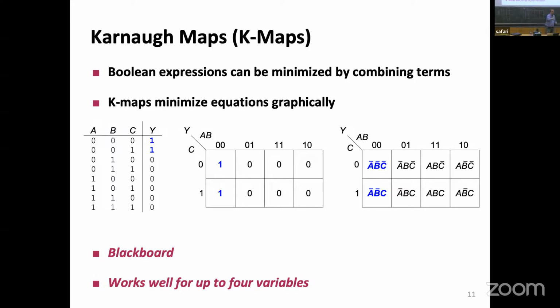Now the third one is where you make all the mistakes. The third one is not going to be 1, 0. Why? Because I would be changing both this guy and this guy. I will make the third one 1, 1, and the fourth one 1, 0. So moving from this column to this column, only 1 bit changed. Moving from this column to this column, only this guy changed. And moving from here to here, it changed. So this is the tricky part.